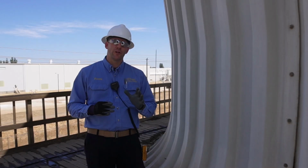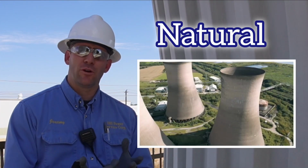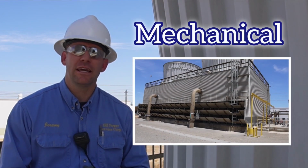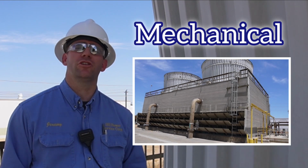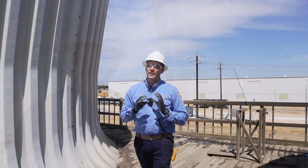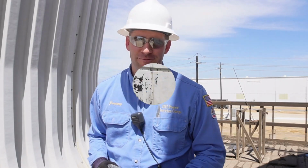Now, cooling towers are usually one of two designs. You can either utilize a natural updraft, and these cooling towers are usually quite large in size, or a mechanical updraft. It could be any size, and they utilize a fan to push air up and out the top, thereby drawing air in from the sides and up through the honeycomb. This tower utilizes a mechanical updraft, and the fans are located right here.